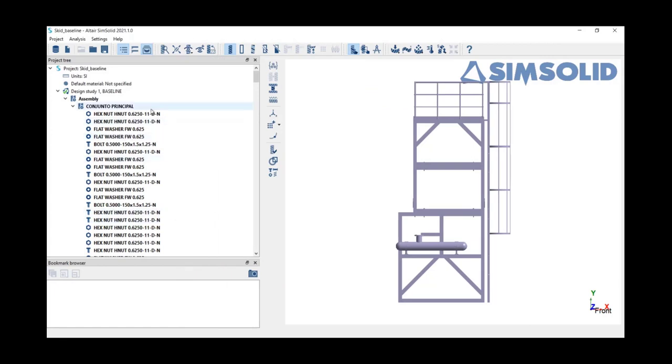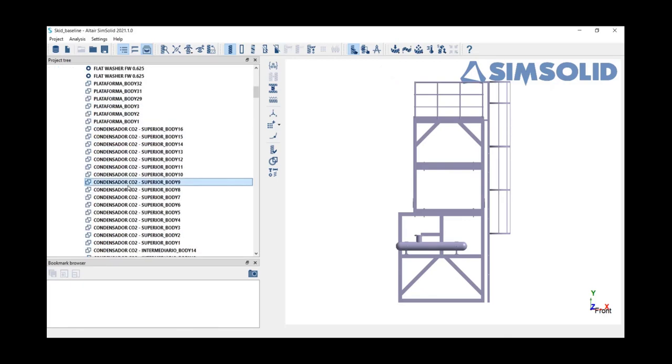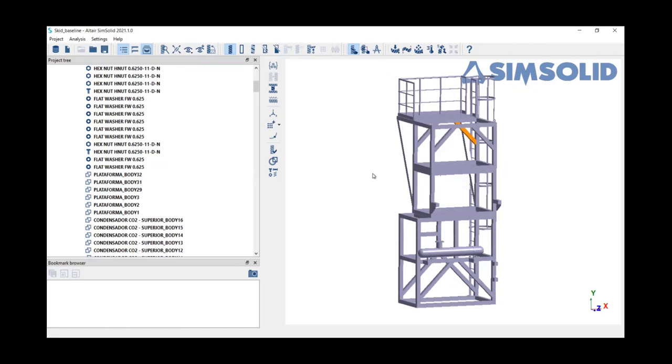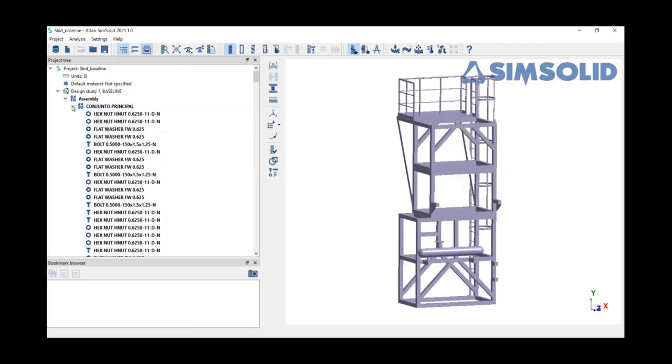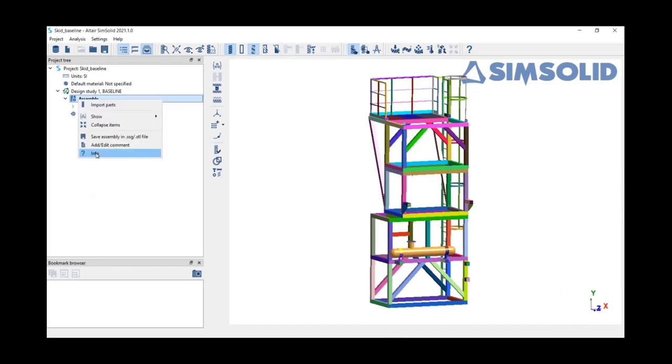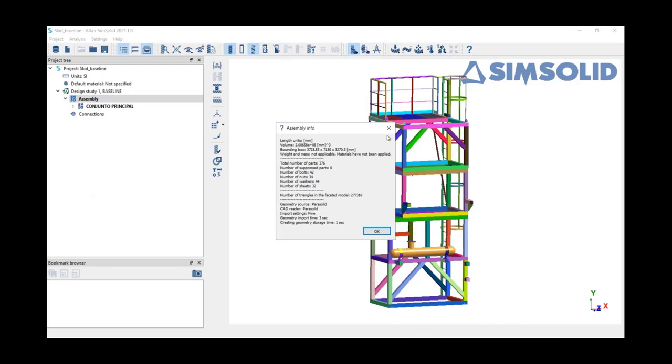So this was just a Parasolid file, but based on the geometry, SimSolid brings us in and says, oh, this part's a nut, this part is a bolt, this is just a generic solid, and that helps the solver later on. So we do the classification up front. Different ways to view this, but as someone coming from those traditional pre-processing tools, HyperMesh, I like all of the colors. This assembly has, let's take a look here, 376 parts.